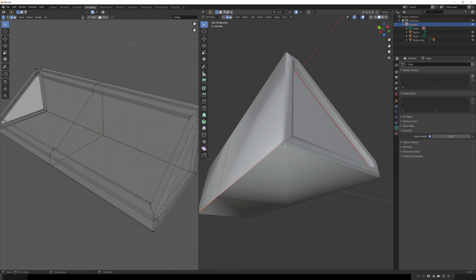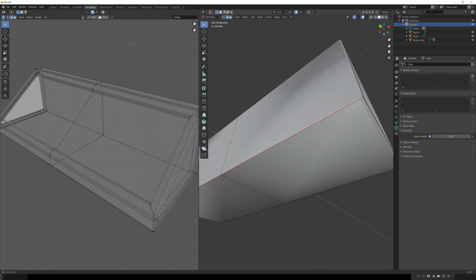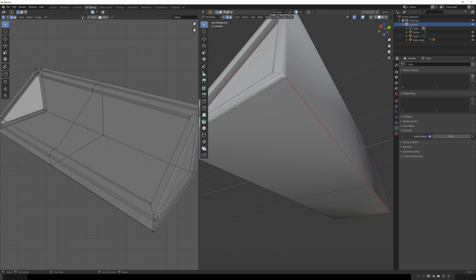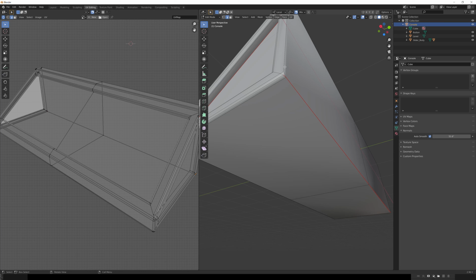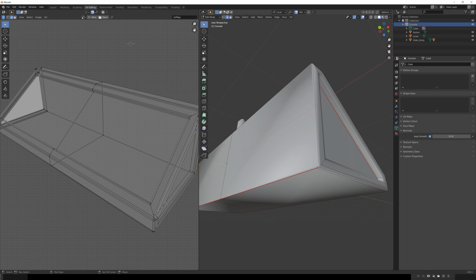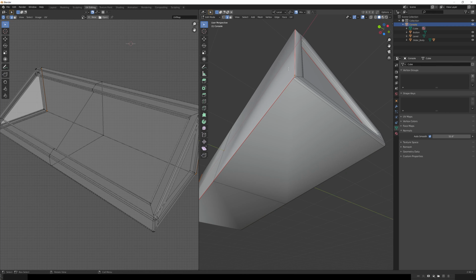If you think about UV editing as, well, as origami, it usually makes a lot more sense in your head as you're doing this. So let's select this one. I'm going to hit Shift and select that one. Let's extend that seam just a bit. And now with that extended, we can come up the side of this object here and here, and here and here. And you don't have to get it right first. So I'm going to do that cut along the side of the object. And now I can see how this is going to start to unfurl.